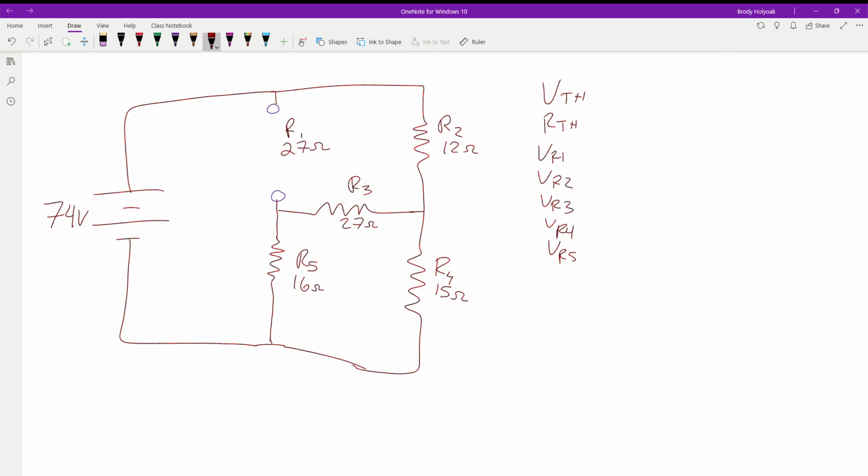So we're going to Thevenize this circuit with R1 removed. Steps are going to be the exact same. We remove the load, we solve for the voltage drop across A to B, and we solve the resistance that these two points would see. Now this is going to change which resistors are in series and which are in parallel when we look back.